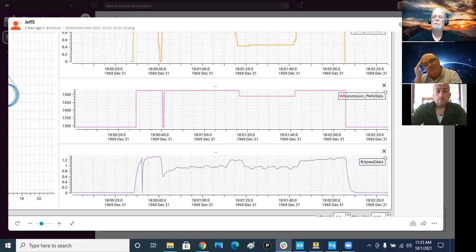So regardless of any PID or feedback on top, just set the RC to a certain PWM and see what the velocity is. Because if that doesn't track, you could try all those correction factors you want, but if it's not working right to start with, you may never get it to come out the way you want.